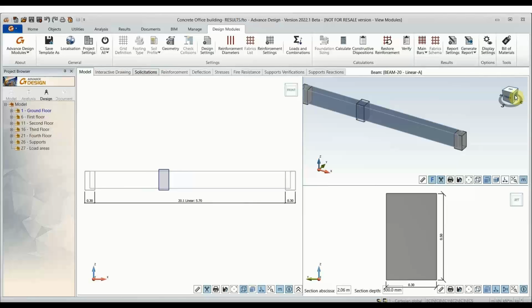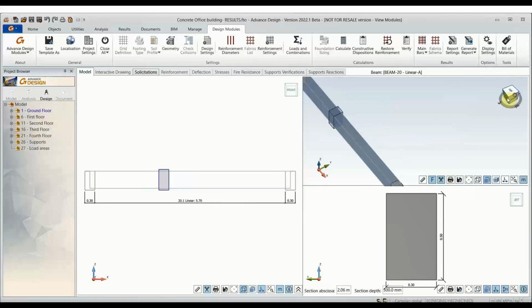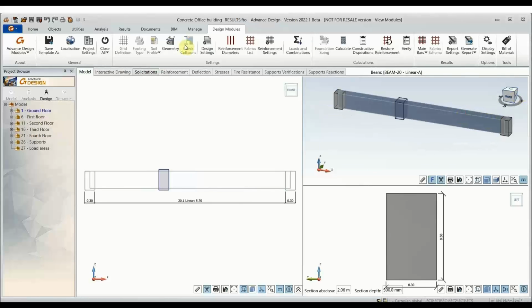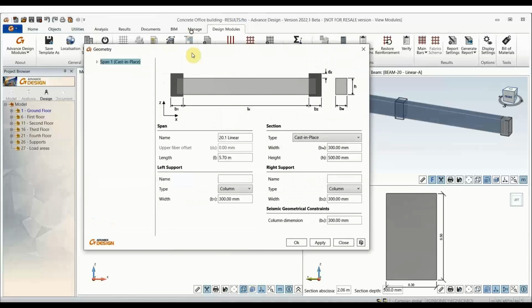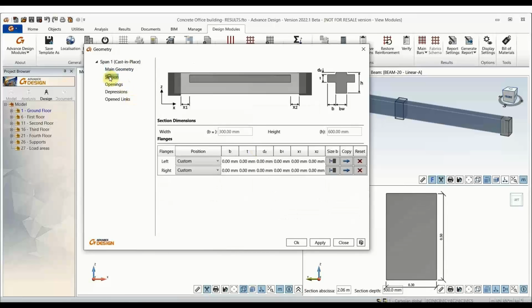Okay. So here, I can design them individually, or I can also put them under groups. So I can design the worst case in that group. So here are the sizes that are imported from the main model, but I can change these at any point. So it's almost as if I'm designing a single member from scratch. So I can define those size settings. Main geometry once again, that's from the model.